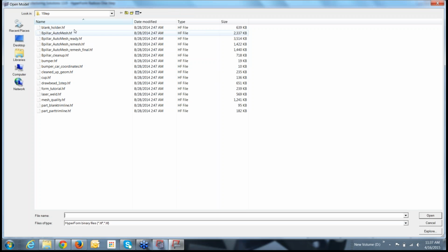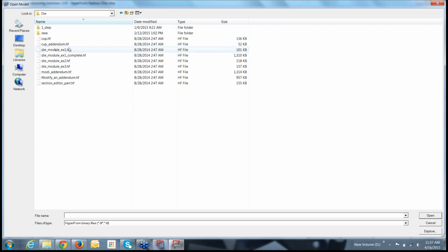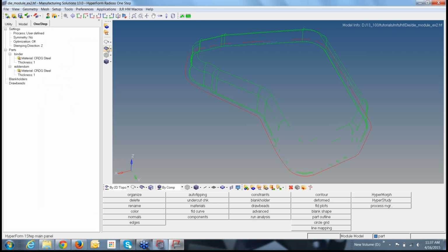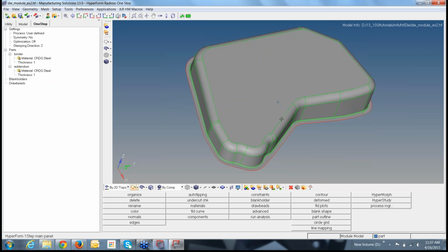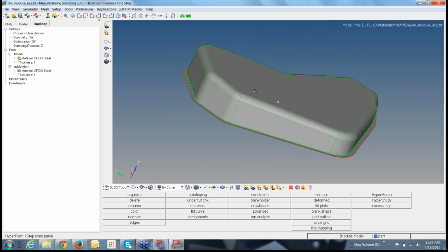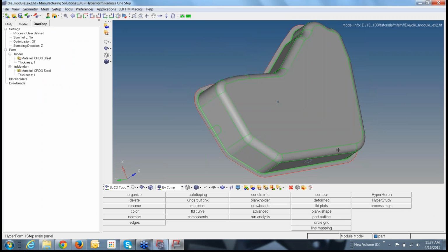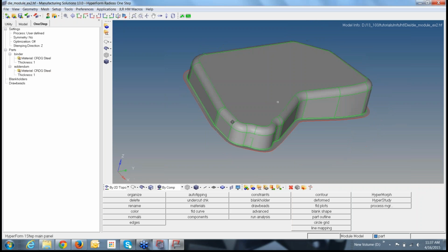Now come to one of the other important options. Once you have cleaned up, you need to mesh, because this is a finite element method. You're not going to run your simulation directly on your geometry. As I was explaining earlier, you need to measure the smallest features in your component and make sure you put it into 2D topo mode so that you do not see any red lines in the middle of your surface, which denote free or disconnected surfaces.